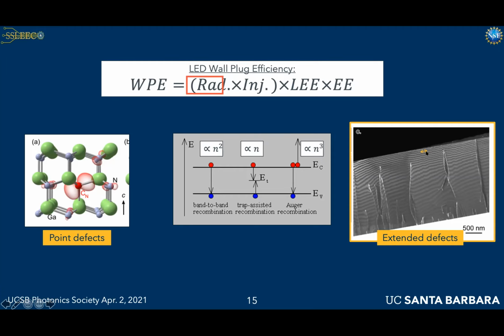This tiny little arrow here that you can barely see represents the diffusion length of a hole in AlGaN. It's quite short, which is good, because if your dislocation density is low enough, like it is in this picture, that the distance between any two dislocations is far enough apart that a hole here doesn't see either of these dislocations, then that hole is more likely to recombine radiatively.